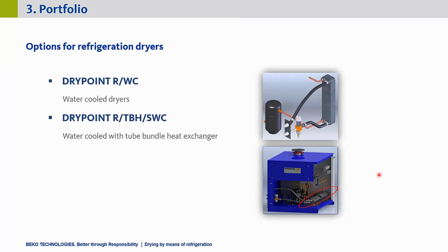surroundings with a lot of particles, or for example seawater with salt and particles in it. As soon as you have this different water, this particle-filled water, then you need a heat exchanger that has bigger space between the plates and therefore does not block. So this is just a heat exchanger that doesn't block as easily as the plate heat exchanger.